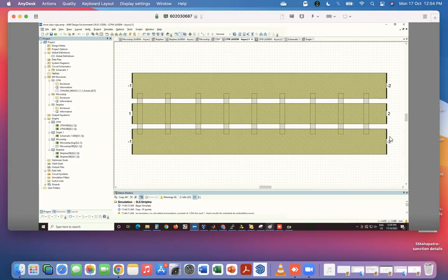So then we can say the quality factor of the CPW is more than the slot line. That's why maybe we don't use the slot line much. The quality factor, yeah, presumably resonances. The resonances here are entirely due to the boundary condition. Quality factor has got to do with the loss in the transmission line due to either the metal or the substrate and all of those things.